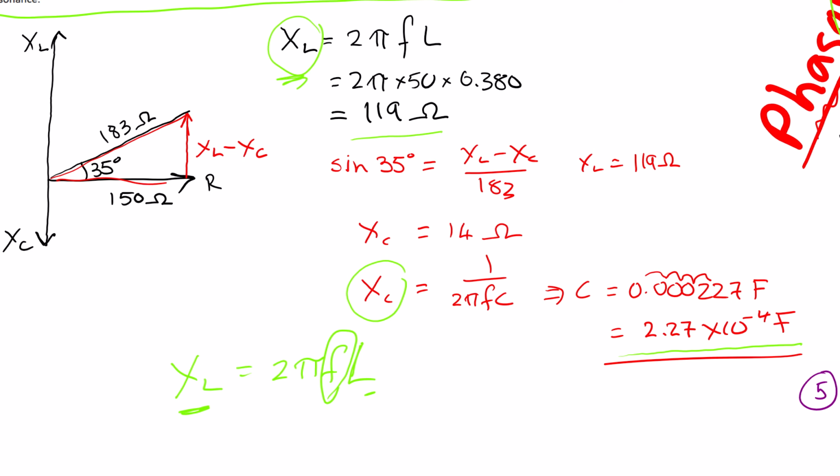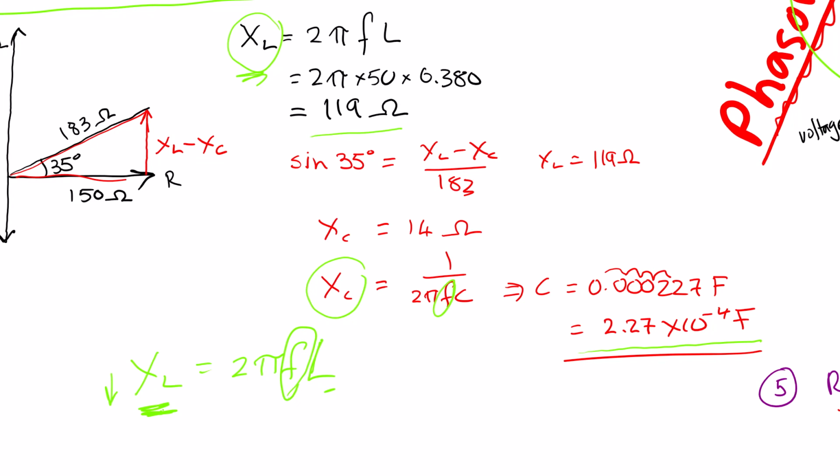If we reduce the frequency, the inductive reactance will decrease. Similarly, if we decrease the frequency, the capacitive reactance will increase. So the inductive reactance will come down and capacitive reactance will go up. So that's the way we can do that.